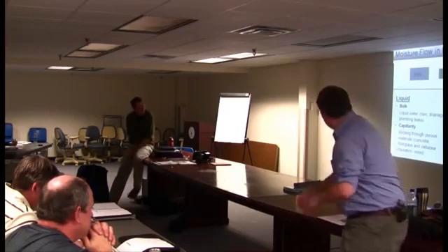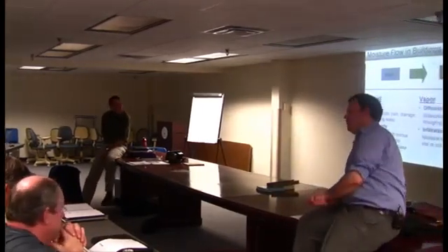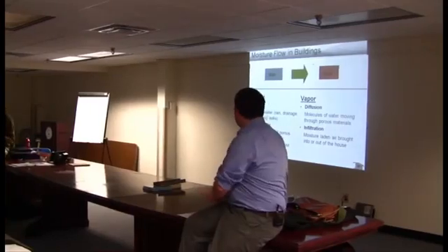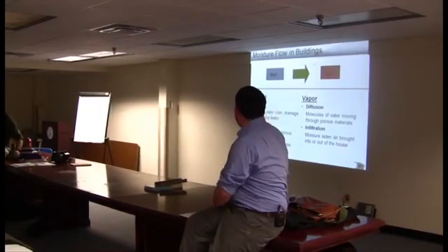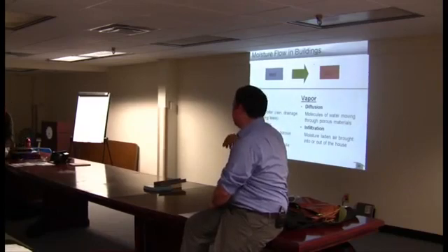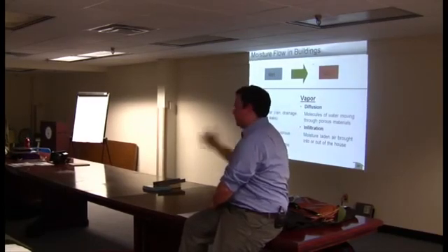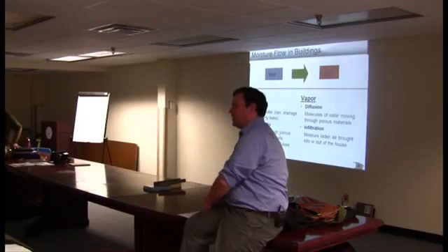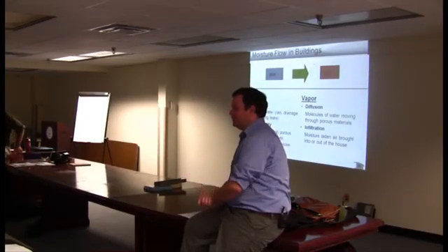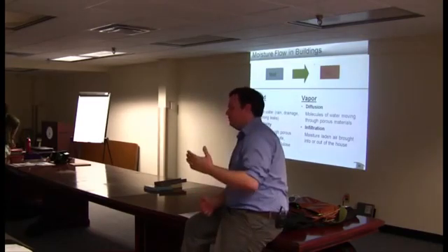And then finally, wrapping up with moisture here. Obviously, moisture is always going to flow from wet to dry. And we basically break moisture into two categories here. We've got liquid and vapor. So over on the liquid side, we've got bulk moisture. These are plumbing leaks, drainage issues. If you've got one of these issues, it's pretty obvious. And we know that it's really important to deal with bulk moisture in buildings.